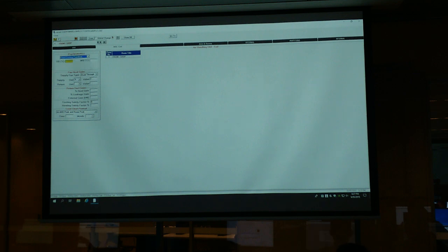If you choose this one, it will be a fixed leaving condition for the supply air, that's the supply air's dry bulb temperature and wet bulb temperature. And then fix the supply air by the volumetric flow rate, and also bypass type.